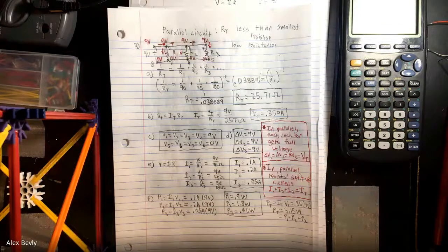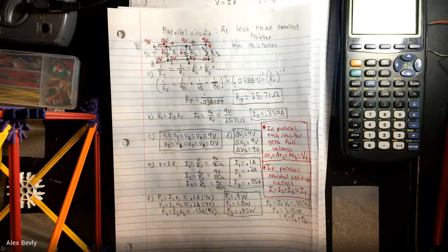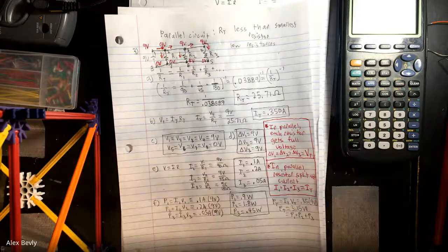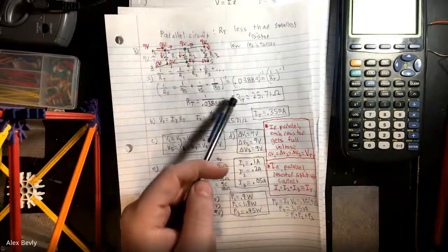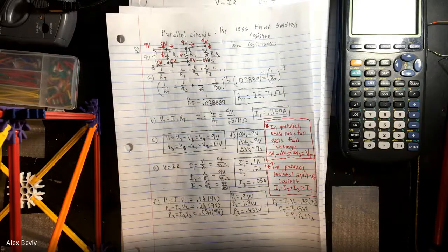This is why you shouldn't plug everything in. Your house is mostly connected in parallel. If you keep plugging things into extension cords and then you plug extension cords into extension cords, then that's happening. You're putting more and more things in parallel. You're adding more checkout lines. It gets easier and easier for the current to flow through the entire circuit as your resistance goes down. You get bigger and bigger currents, you get bigger and bigger powers, and then your electrical outlet catches fire.